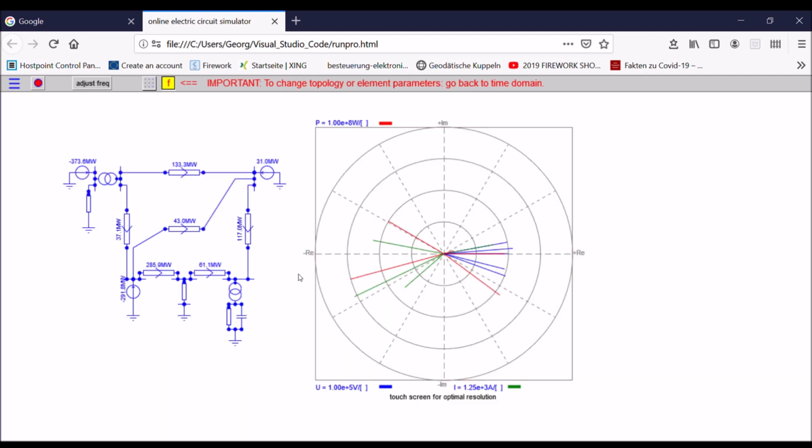And what you see here now is the contribution from the slack bus. The slack bus has 0 voltage angle and 200 kV, and the other buses are what you can see here and here, and you see also the corresponding power input at these other buses. So this is what I wanted to demonstrate here. You can do it manually, so you learn about the whole system.